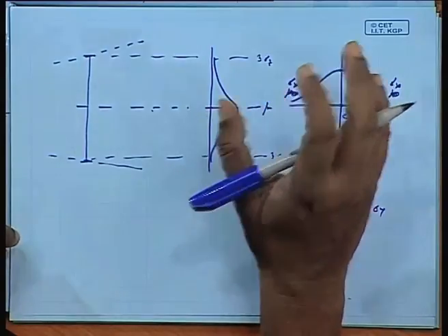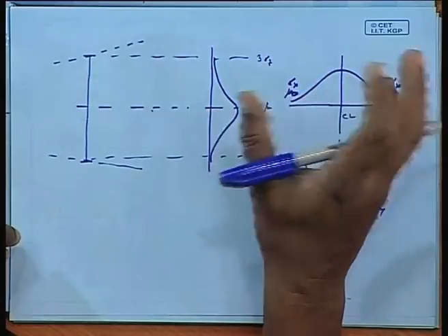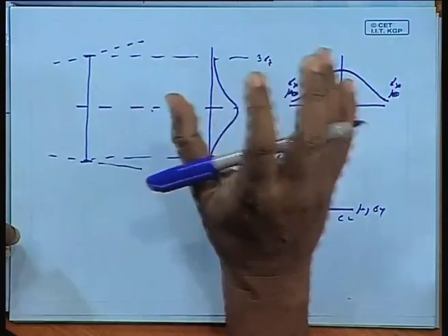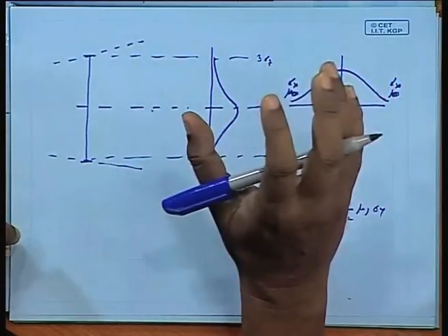When we say a plume and when we say a Gaussian plume, the essential difference is that in the Gaussian plume we consider that in the x, y, z directions, the concentration of the pollutants is normally distributed.